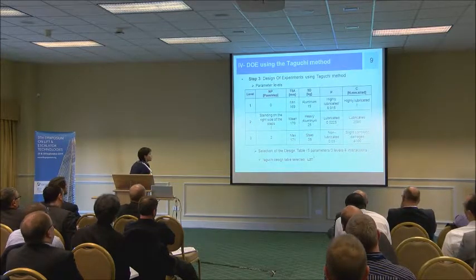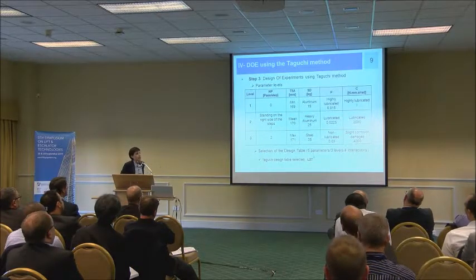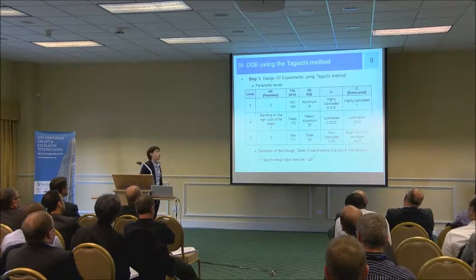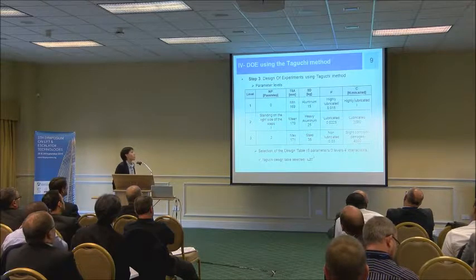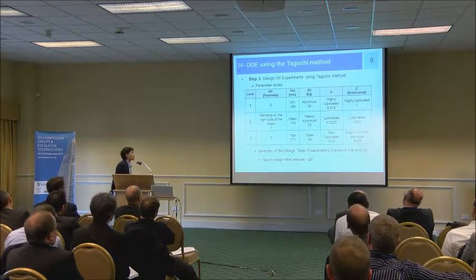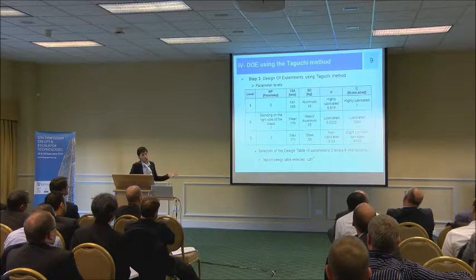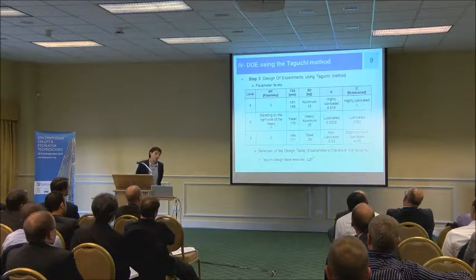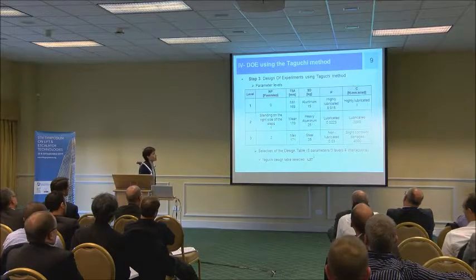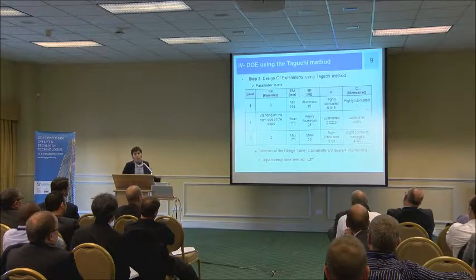After this, we decided to run a second set of experiments using these 5 parameters, this time to assess their impact on the dynamics of the system. Given the computation time, we decided to perform a design of experiments. Based on the previous results, and given that one of our parameters is nonlinear, the position of the passengers on the steps, it seemed more interesting to focus on the study of the linearity of the system rather than a high number of interactions between parameters.